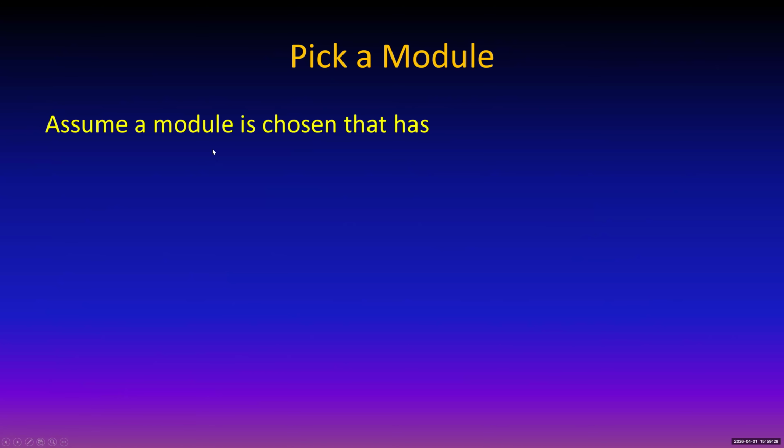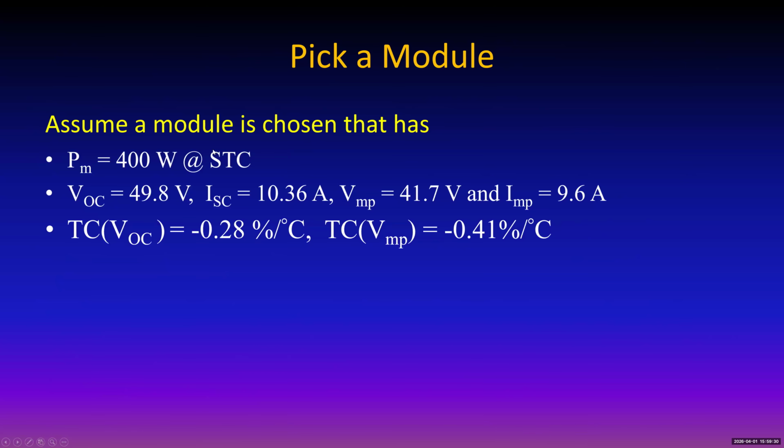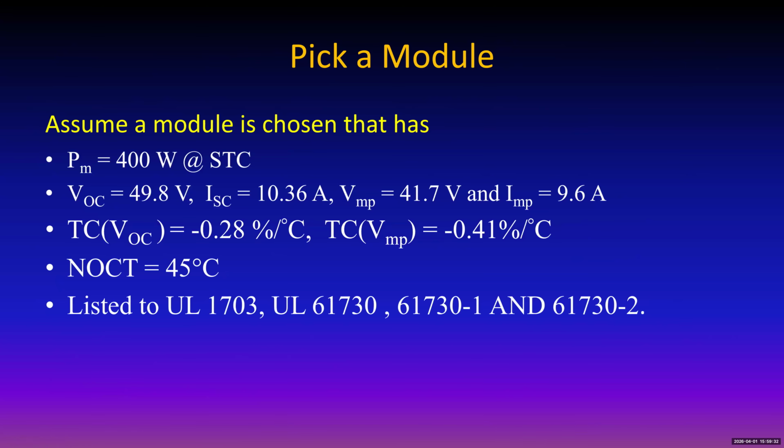First of all, you've got to make sure that for any one maximum power point tracking input in the inverter, and oftentimes now the inverters have more than one maximum power point tracking input, for each maximum power point tracking input, all of the modules have to be facing exactly the same orientation. The string lengths don't have to be identical. There's a maximum and minimum number of modules per string.